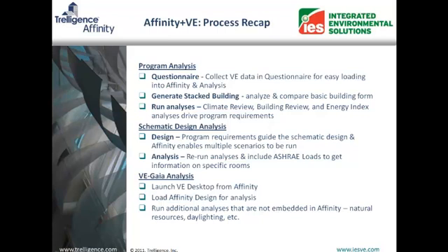And then, with the program and stacked building in place, we can run climate review, building review, and energy index analyses to get some initial feedback about our program and the basic rectangular stacked building. The results then help to drive our additional program requirements or change those that we've set up earlier. We use the program requirements to guide our schematic design.